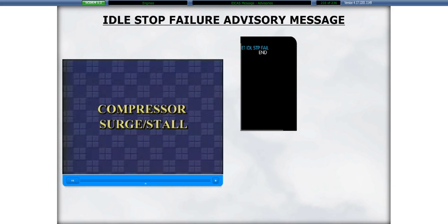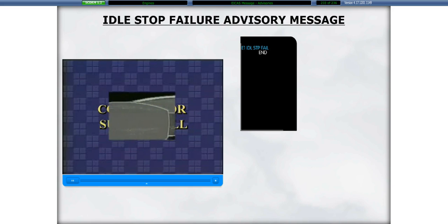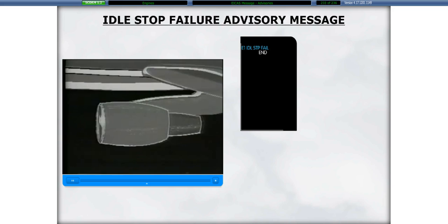From a flight crew member's perspective, one of the most startling events is the engine surge or stall on takeoff or during flight. An engine surge is, in the simplest terms, the breakdown of the airflow in a turbine engine. When the compressor blades stall, they are no longer able to force the air through the engine from front to rear. Now the high-pressure air in the middle of the engine can escape explosively from front and back simultaneously.